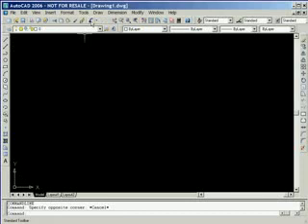There are two other toolbars that are currently displayed on the screen. The standard toolbar is displayed horizontally, directly below the pull-down menu options. It contains frequently used functions such as the undo option shown here. The other toolbar that is available on the screen, as it is shown here, is the Modify toolbar. It contains the erase icon as well as other icons that will allow us to make changes to our drawings. Later in these lessons, we will learn how to customize the interface and add additional toolbars to our screen.